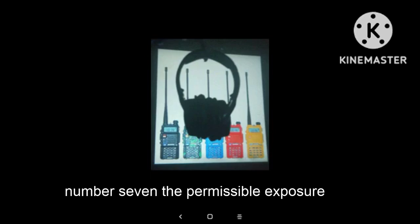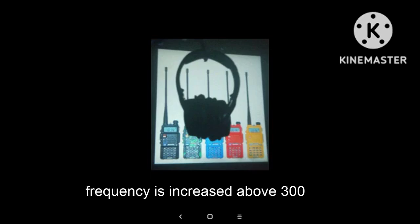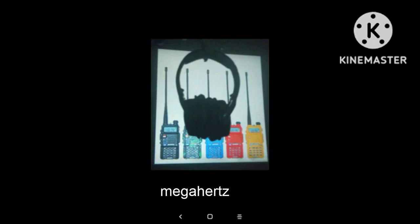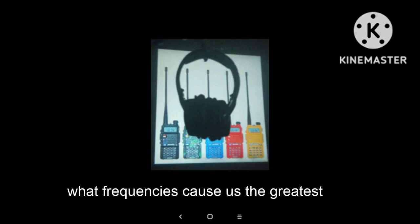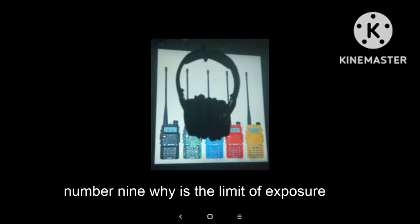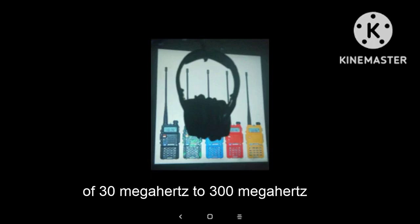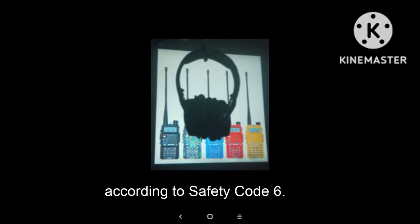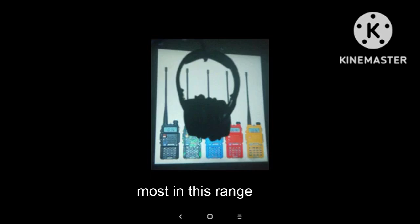Number 7. The permissible exposure levels of RF fields increase as frequency is increased above 300 megahertz. Number 8. According to Safety Code 6, what frequencies cause us the greatest risk of RF energy? 30 to 300 megahertz. Number 9. Why is the limit of exposure to RF the lowest in the frequency range of 30 MHz to 300 MHz according to Safety Code 6? The human body absorbs RF energy the most in this range.